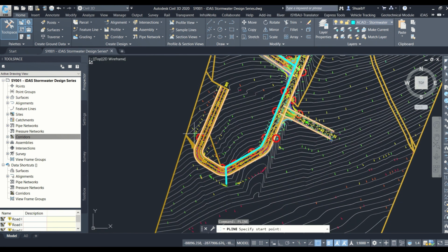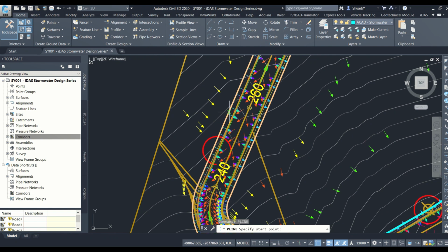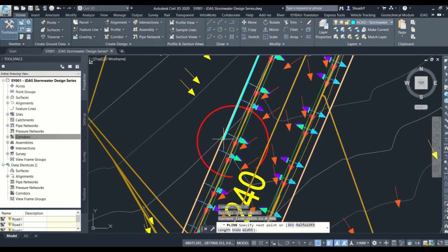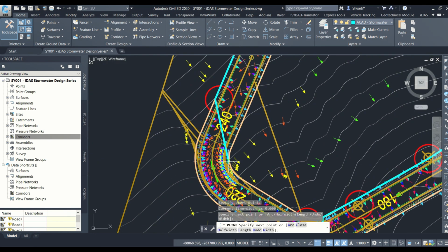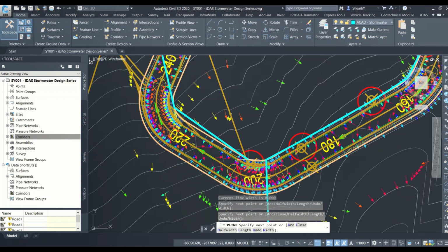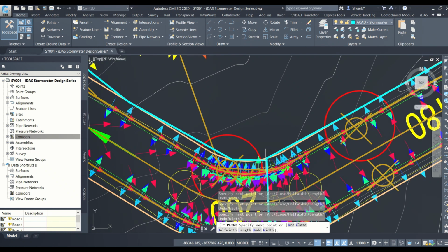Let's do another polyline branch. So let's do the one coming down. Here the water is going to be flowing from about, let's say there. I'm going to have a manhole drop in there, come into the curb inlet, or just come into the curb rather. I'm going to tap there. It looks close on screen, but it's in meters, right? You'll see the pipe lengths are quite long, but when we do the optimization, it'll be pretty good. Right, and I'm going to tap in at that junction.